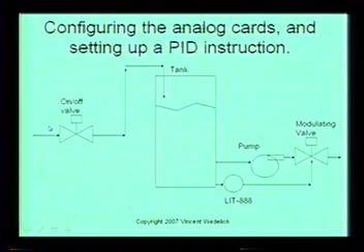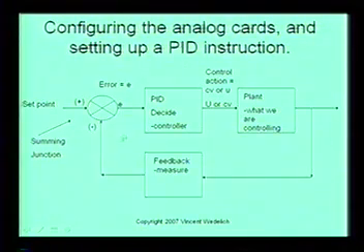So here we actually have a pictorial example of this. This is really controls, and this whole controls idea. If you take that FE EIT exam, you're going to have to do this a little bit more, and you probably have to take one of the quick courses that I offer on controls, because it goes into a lot more detail than anybody that's learning PLCs would want to go into. But this is just a basic idea, and every PLC programmer needs to understand the basic PID instruction. Now you can actually have a PID and then after it another PID, and that's kind of like a cascaded control PID.